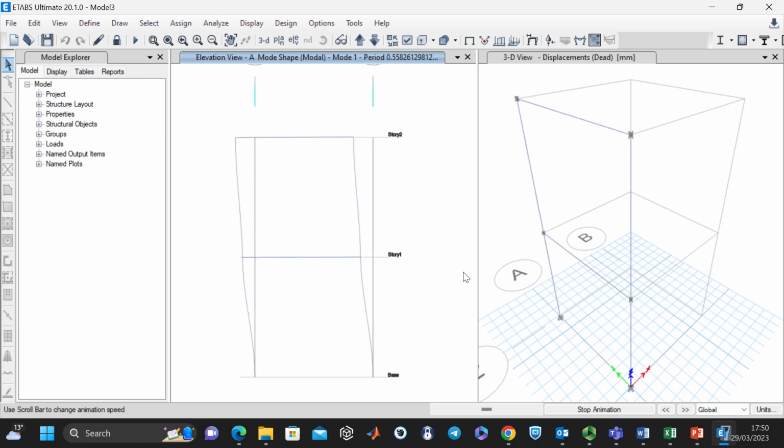It's vibrating. So again, I emphasize that this is not the deformation of the structure under any certain external forces. It is the mode of vibration. It's some sort of inherent characteristic of the structure depending only on the mass and stiffness matrices. But it is the main ingredient to produce the final deformation of the structure under any certain dynamic forces.